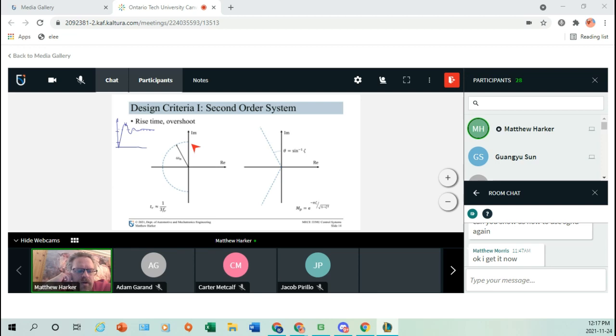Right, so our general rule there is something we basically derive from a simple second order system, right? So the system we looked at, where we had a spring, a mass, and a damper, and we pushed on the spring side, and it moved the system around. We would take that as a base system with two poles, right? And because we're only looking at two poles, it's in essence a second order system.